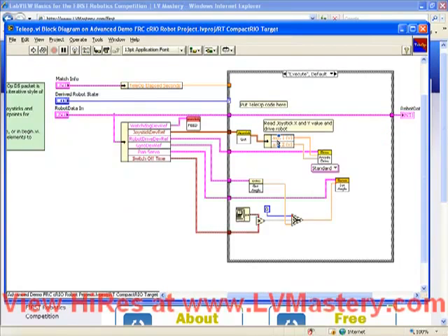I've had the opportunity to observe a lot of new LabVIEW programmers, and one of the most common problems I see is very simple to solve, and it's just about wiring techniques and wiring style. Let me give you an example. Let's delete and then redo the wire from the switch off time in the unbundled by name function to the bottom terminal of the comparison function.